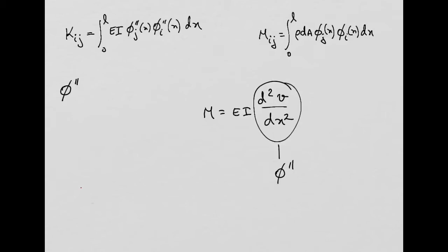So for the polynomial functions that we choose, or the shape functions that we choose, there are some rules. They need to obey the boundary conditions, always, okay? They need to be linearly independent. They need to be a complete polynomial. This kind of thing. I'm not going deep into that because I just want to give you some idea, and you are going to study that further in FEA as well.